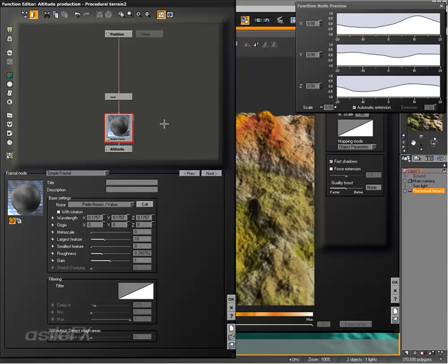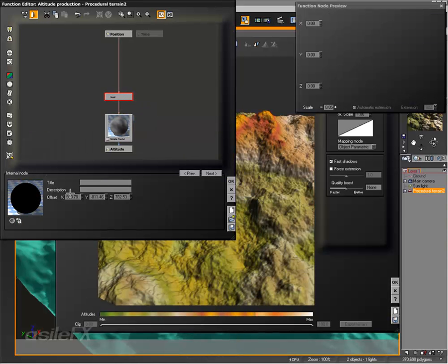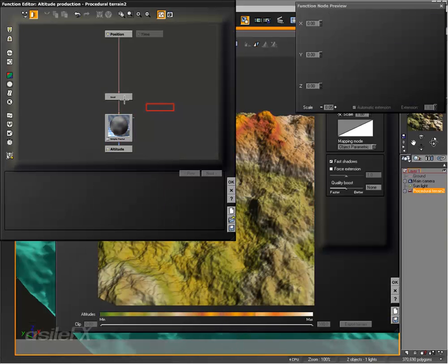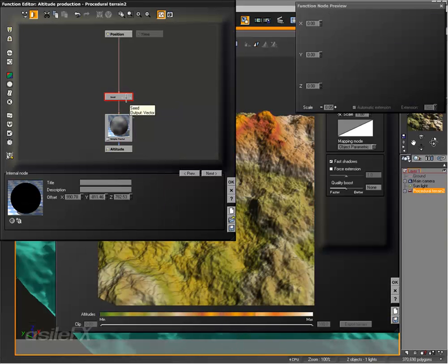It works in the reverse direction. So if you do need to keep this seed offset amount, because you like the terrain you have, you can copy the values from the seed, paste them into the origin, and then if it's a positive, you just put a negative in front of it. If it's a negative, remove the negative dash and make it positive, and then it'll match up.